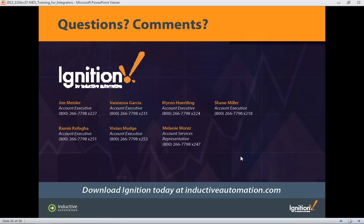So 50% of the time we're utilizing it, the other 50% of the time we are not utilizing that asset. Then, while we were utilizing it, we take what the OEE was during that time and factor that into it, and we come up with our TEEP figure. So if we had perfect OEE and we ran all 10 days over this 10-day period, we would have 100% TEEP because we're utilizing that asset to the fullest extent.